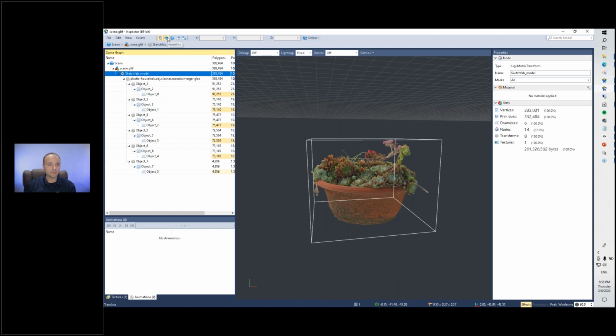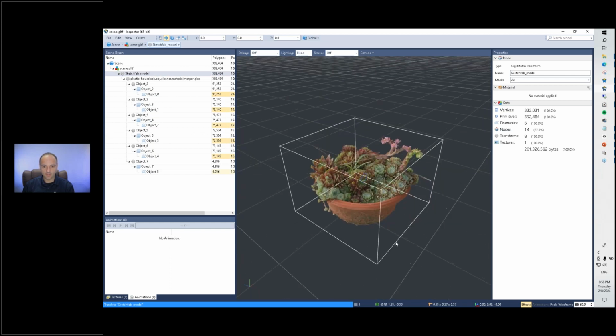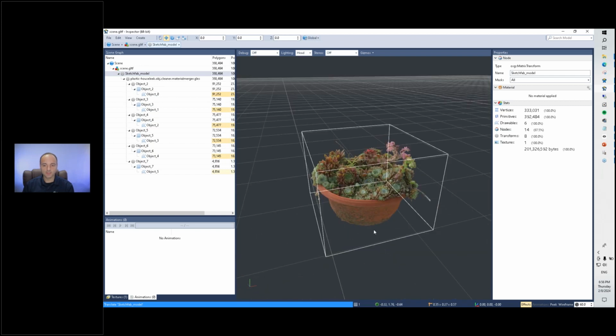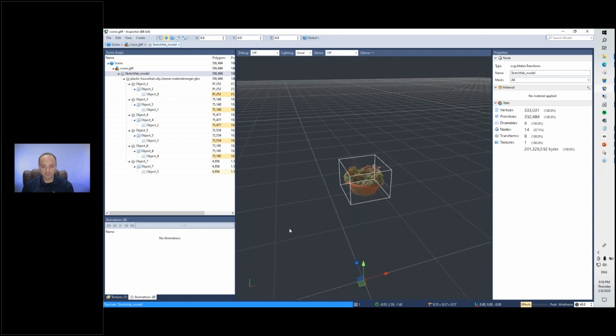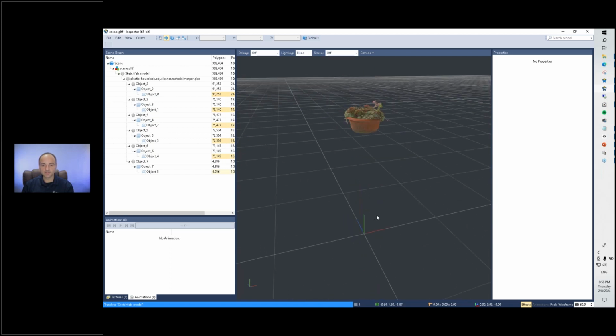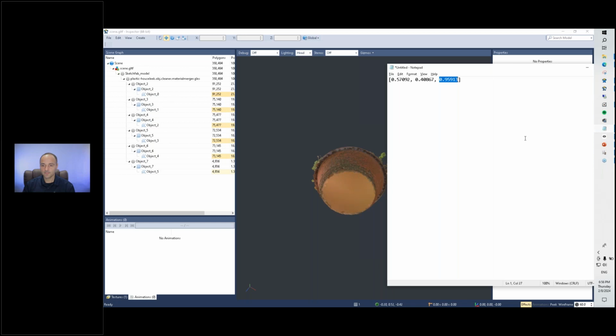And to do that, we check here. It's just completely not at the origin. So I change everything to 0, and there we have it. It's right here. It thinks it's at the origin, but it's not, because there is some sort of offset with this 3D model. This here is the origin of the world, right here. So there's a little trick. I can go and look at the bottom of this object and copy the 3D position. And now I know that it's offset by this much.